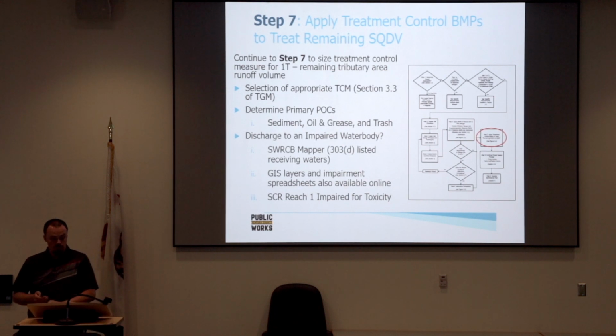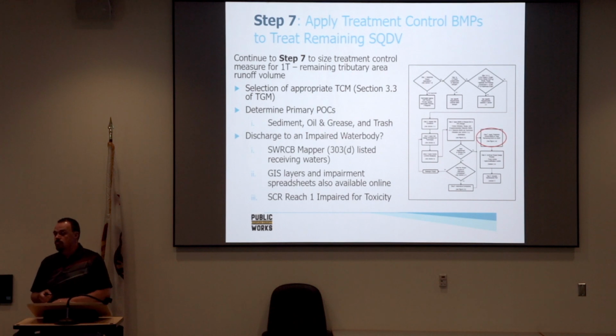Yes? To answer Shada's question, table 6-6 of the bioretention design criteria. Maximum drawdown time of water ponded on the surface is 48 hours. The maximum drawdown time of the surface ponding plus the subsurface pores is 96 hours. Yep. With a 72-hour buffer. So the calculation for the 48 hours is the maximum drawdown time of the surface.